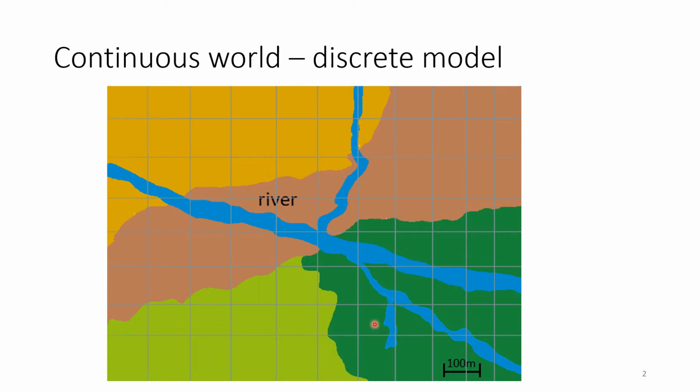I could resolve that, for example, with a finer resolution. That means smaller cells, more of those cells. And this, of course, would increase, in some way, the quality. I'm being careful with this word, but for now, for the introduction, you might have an understanding of it: I would have higher spatial resolution, maybe being more accurate. Accuracy is also something we will talk about within this course. Be careful with using this word. But of course, when I have more cells, I have to do more computations, because for each cell I have to solve my differential equation. Having more cells means more computational load. This would, on the same computer, increase my workload. But this is the idea.